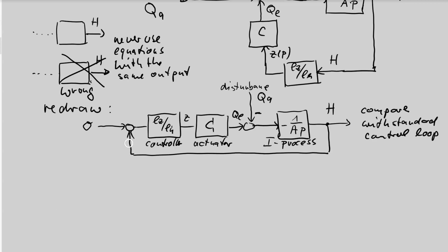Here is the plus sign, but negative feedback we have in any case if there is one minus sign in the loop. And you see here the process has a minus sign caused by the equations. This minus sign gives the negative feedback, so this system really works. And you can believe me that this works because this works in every water toilet.